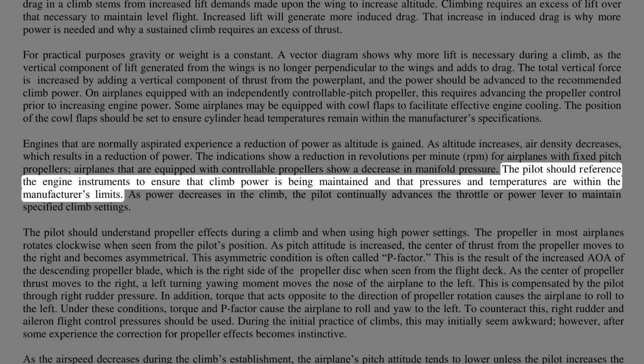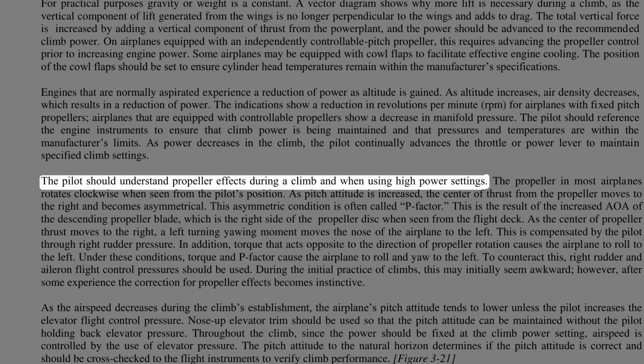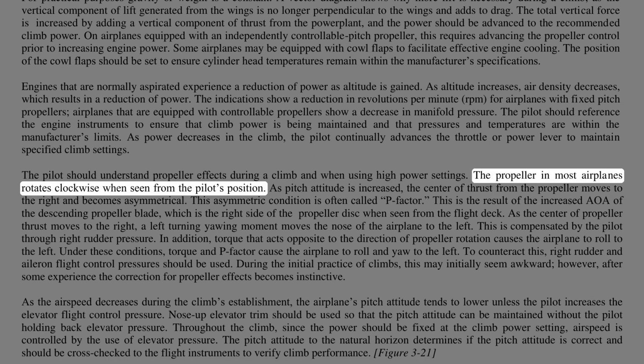The pilot should reference the engine instruments to ensure that climb power is being maintained and that pressures and temperatures are within the manufacturer's limits. As power decreases in the climb, the pilot continually advances the throttle or power lever to maintain specified climb settings. The pilot should understand propeller effects during a climb and when using high power settings. The propeller in most airplanes rotates clockwise when seen from the pilot's position.